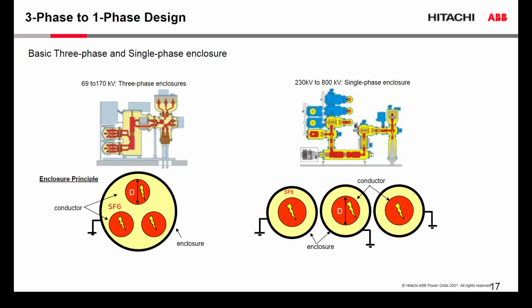You have fewer density monitors, a lower number of mechanisms for disconnect switches and circuit breakers, and a lower amount of cabling with such technology. A lower amount of modules means automatically also a lower failure rate. So automatically the mean time between failure of such technology will increase.